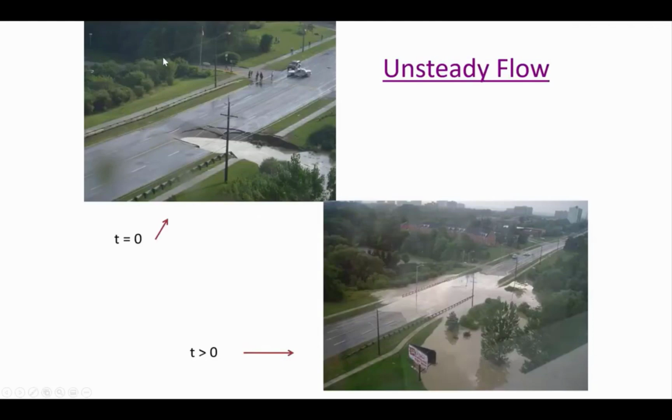And I've got a picture here of a before and an after of a culvert failing. In this picture, what happened was that the water level was rising on the upstream end of the culvert. So the water can't flow through its normal creek that used to be there because they put a road in on top of the creek.